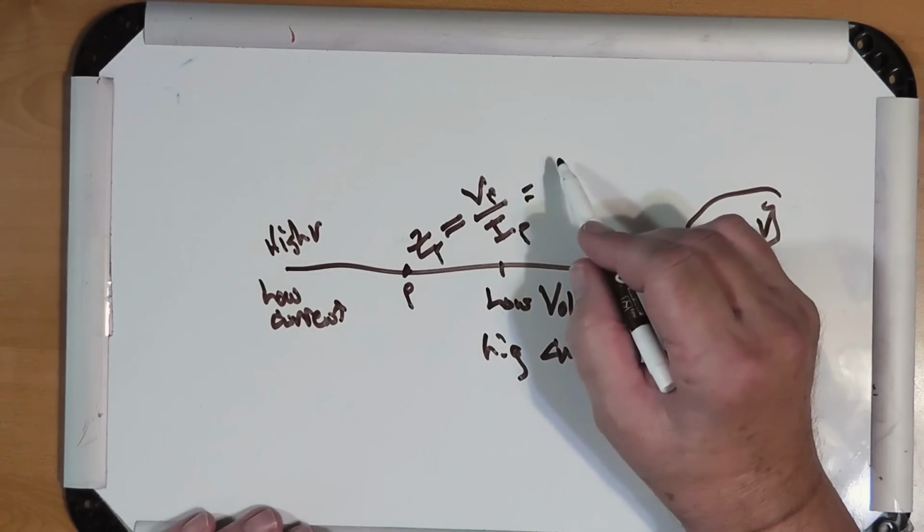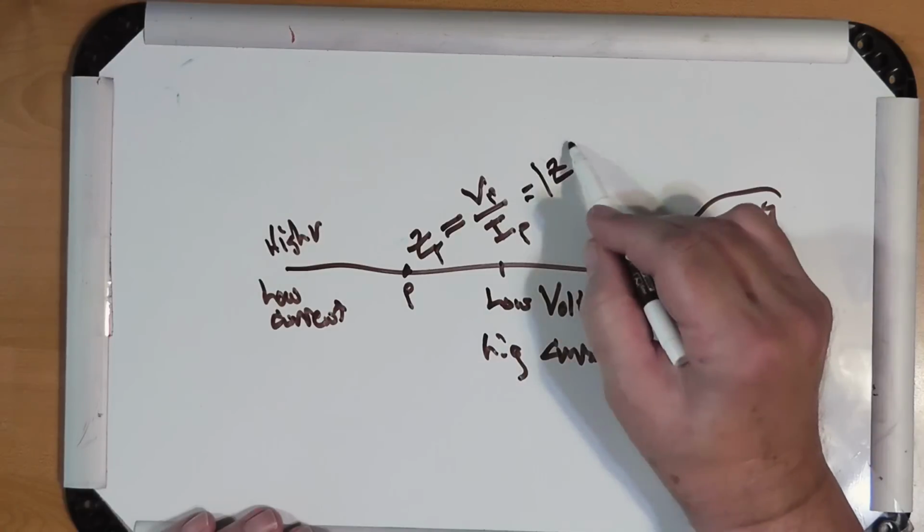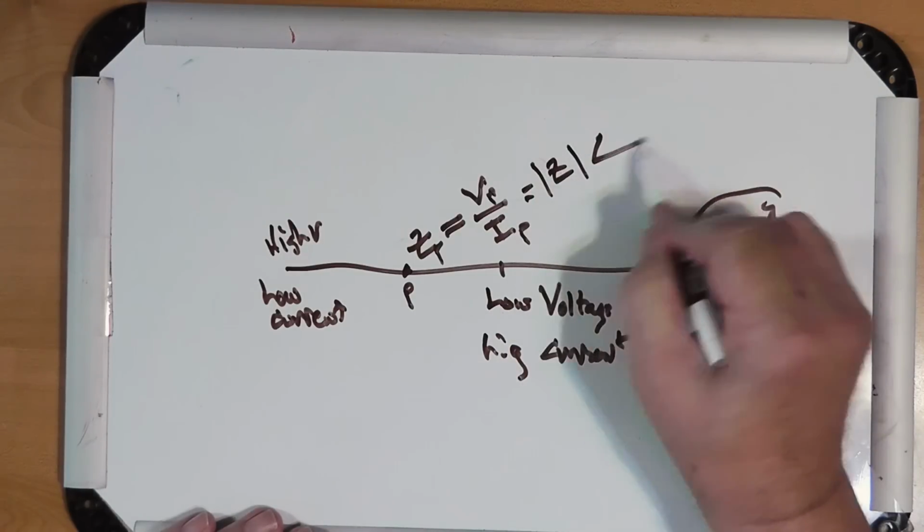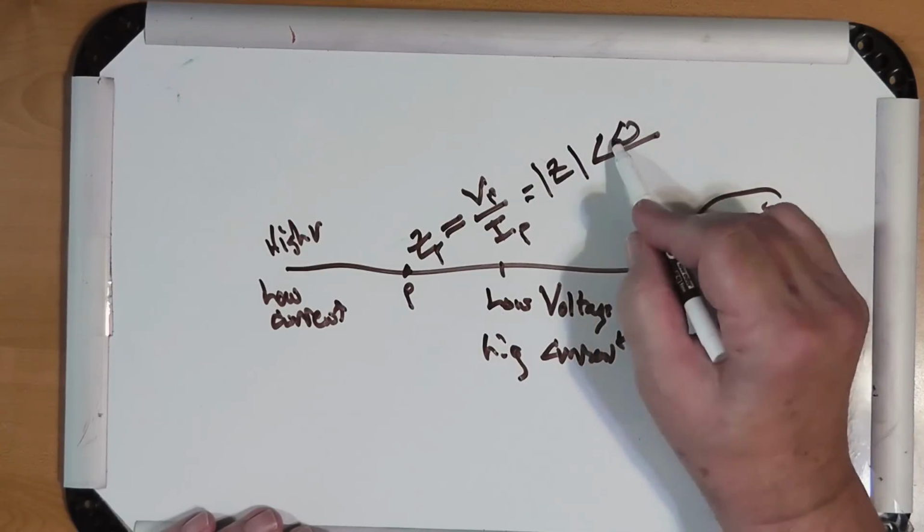What we would like at the center is 50 ohms at 0 degrees phase. We're not going to get that. In actual systems, if this is a true dipole, meaning a true half wavelength, this would be more like 37 degrees here. Okay, but the point being that the whole antenna radiates.